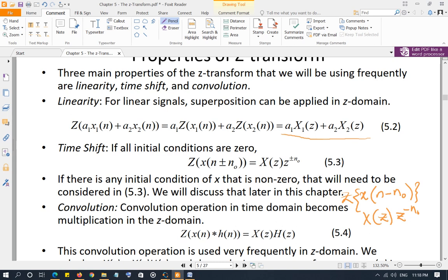That is, when we do the output using Z transform of x and Z transform of h, so basically y of -1, y of -2, x of -1, x of -2, if those are 0, then basically you can write the Z transform of time shift by this, and if you have a plus sign, of course, then it's going to be a plus sign over there.